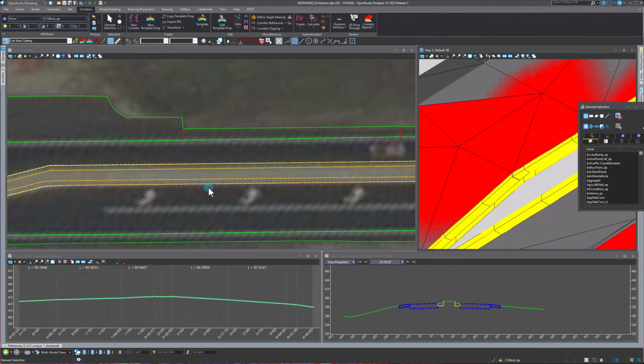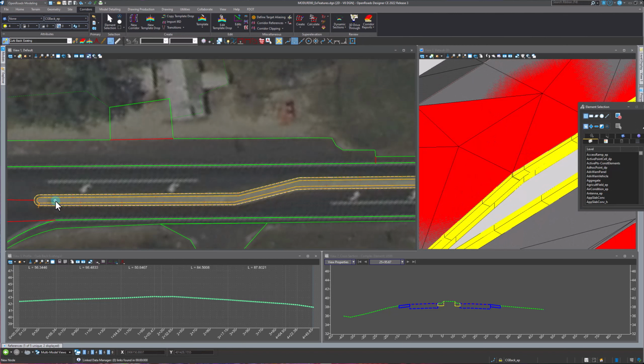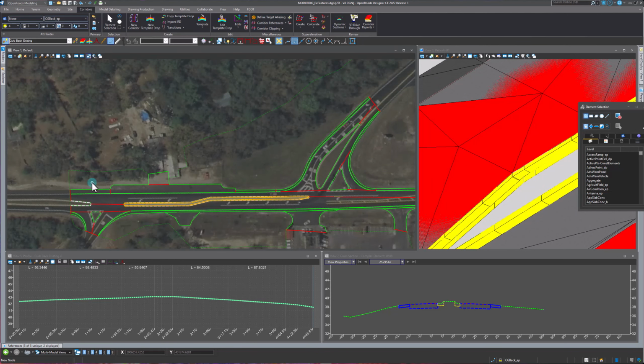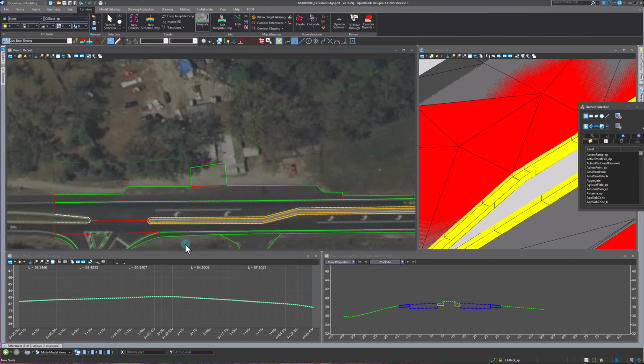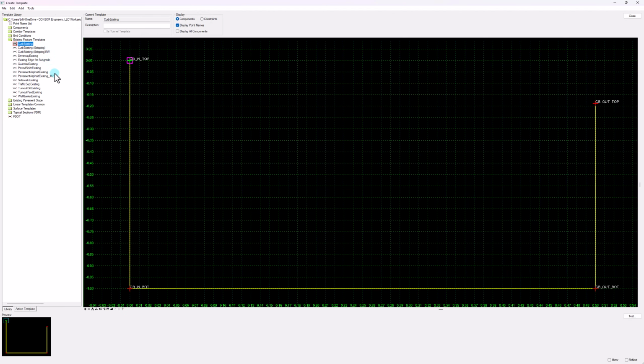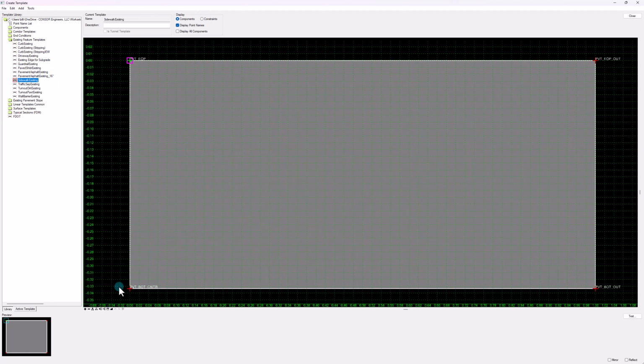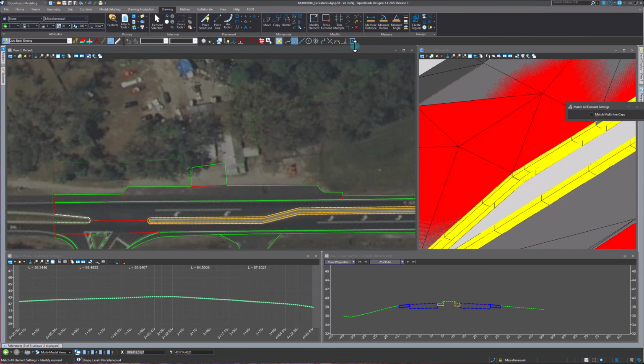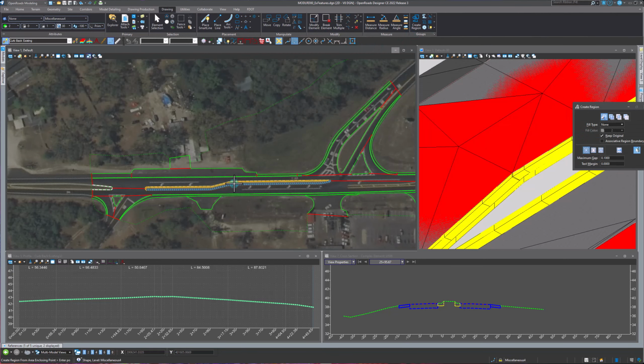Right. Now what I think is happening in here is this area is filled with concrete. Let's go look at the templates we have real quick. We can probably use something like sidewalk concrete, which is 4 inches, or we can use the driveway existing. I'm guessing this is probably like 4-inch concrete. So let's just use that sidewalk template. But first we have to make a shape in there. So let's go ahead and get a shape in here.